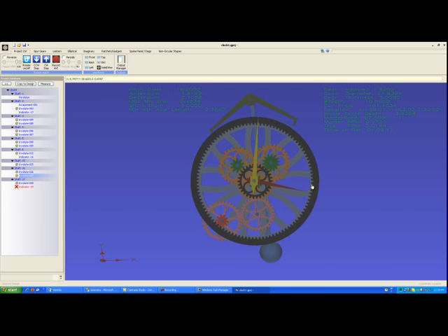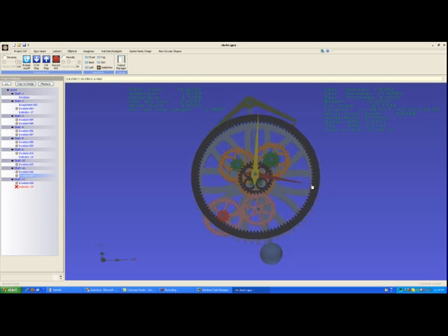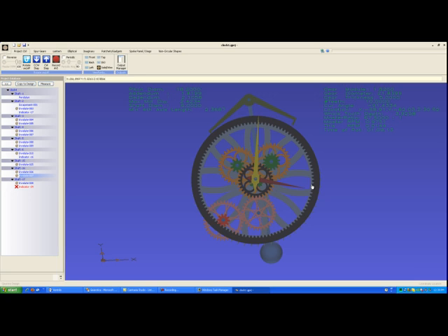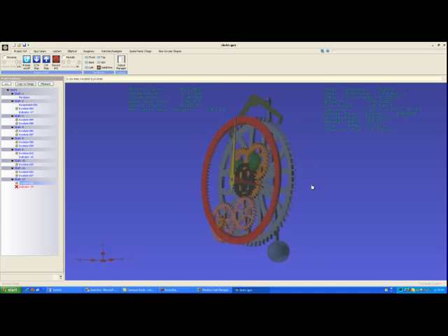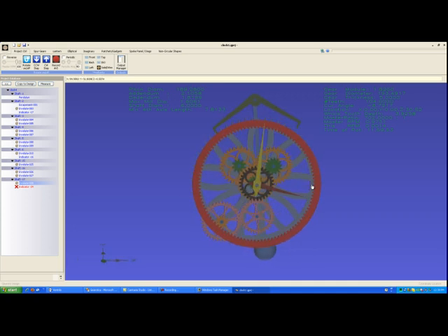So I added a planetary gear to the outside. It's a 104-tooth planetary gear meeting a 10-tooth, and it brings our ratio up so that we now have 11 hours and 59 minutes for each rotation of this planetary gear. My thought was either to laser print numbers on the wheel and put a large magnifying glass so that the hour is rotating in, or to simply add an indicator to the wheel, which is a pointer pointing in, and it will point at the numbers as they go around.